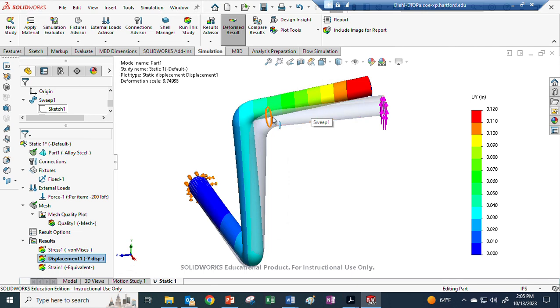But you can get insight by hand into what caused each of these deformations that you can't get with the FEA. So say you wanted to redesign this to minimize its deflection, you know the causation, the major drivers, and you could change it accordingly. Maybe make one of the diameters bigger than the other, whatever. All right, let's